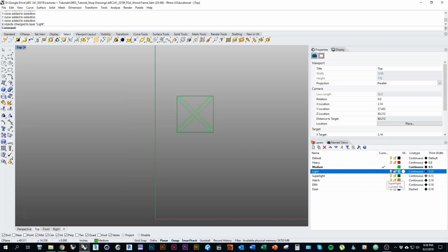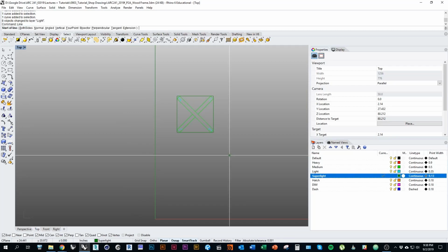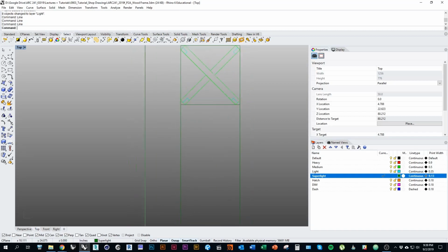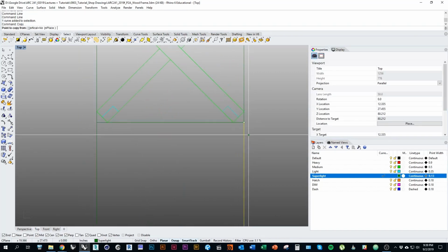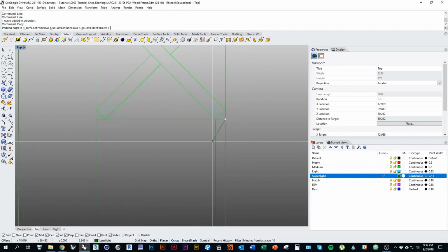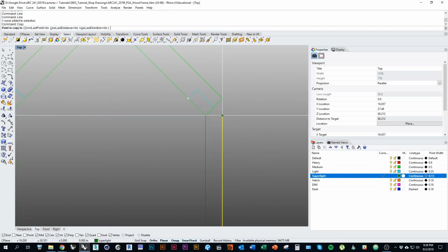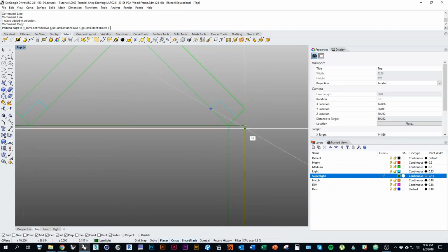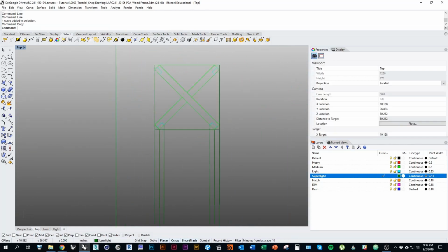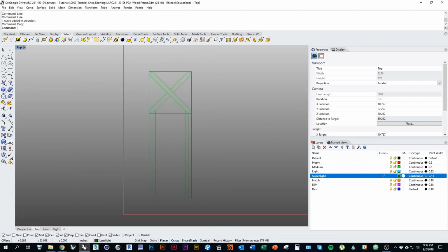Before I get started with that, I'm just going to draw a couple of construction lines. So I'll set my super light layer to current, draw a line, just draw it down. Doesn't matter too much the length. And I can actually copy this line just so I'm a little more consistent. Now I want to make a construction line that's going to show me where I need to draw every edge in this case. So I want to go ahead and make a construction line for that edge of the joint. I already have one for the outside edge, and then for that inside edge. So I'll copy it to those two points. Okay. And that's going to be the template for drawing our verticals in our elevation.